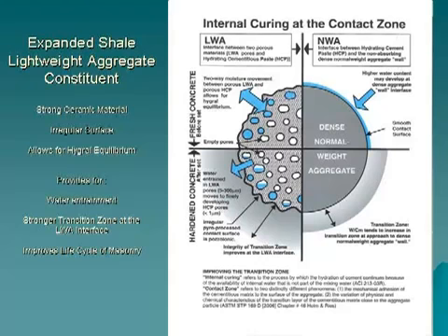During the wet batch mixing and then molding of the lightweight block, a certain percentage of the mixed water is absorbed at the surface of the lightweight aggregate. This seeks to combine with any water already present deep within the particles. Empty pores serve as reservoirs for the absorbed water. In the hardened state, the water in the aggregate particles serves to improve internal curing. The transition zone, the area around the lightweight particle, remains at a low water-cement ratio, therefore improving the bond strength on the irregular contact zone.